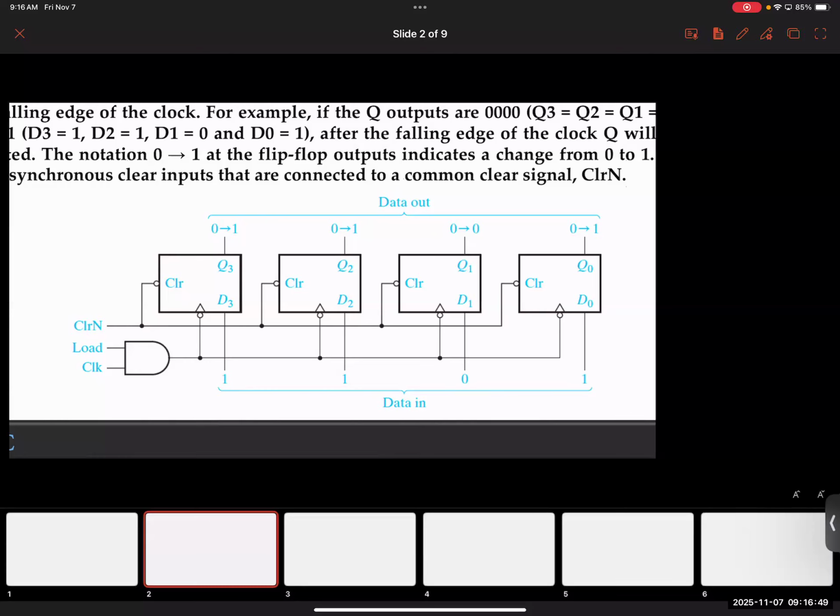But imagine if you keep your load signal at 0, and this is an AND gate. Your clock, no matter if it is 0 or 1, doesn't matter, the output will always be 0 because it's an AND gate. So you'll never have a clock activation, so nothing will happen. So essentially, this load signal, although interesting, the fact is, on chip, the clock is always oscillating. You cannot stop the clock. It is shared with so many different components. It is always oscillating. How can you kill the clock for a specific register?